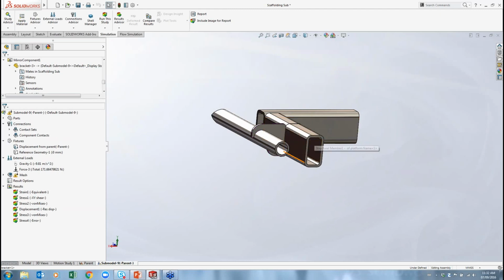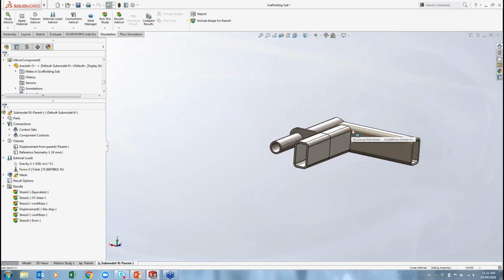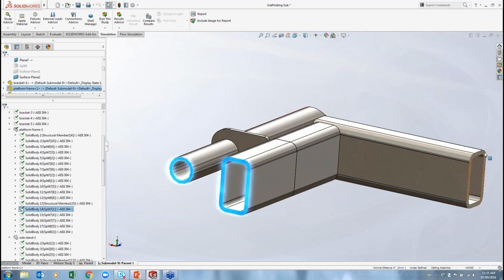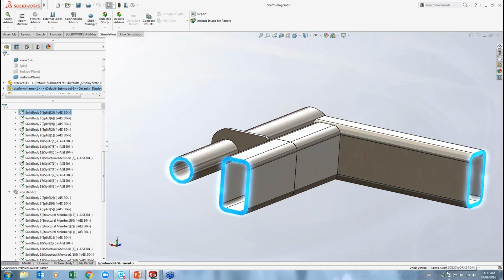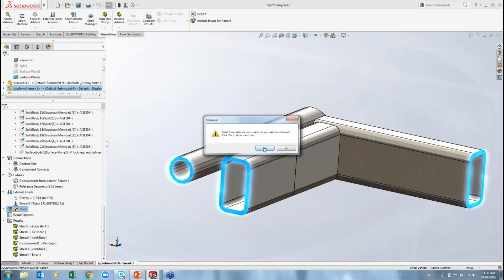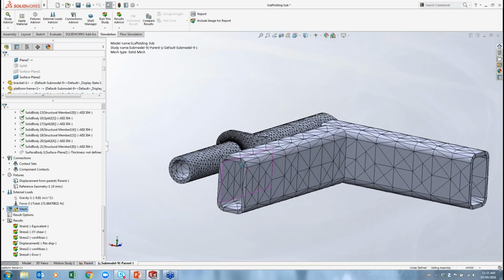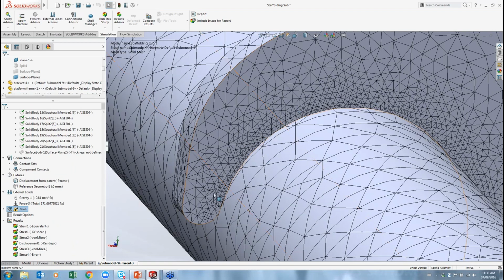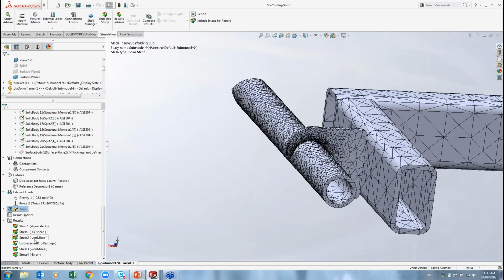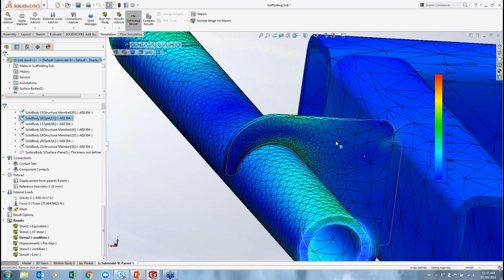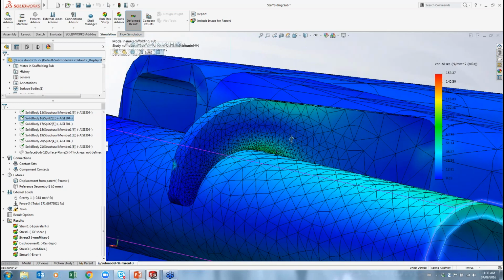Just a few components, but we can see very detailed results on these. Again, the boundary conditions at all the edges here, at all the cut faces, these faces are deforming and behaving like they're connected to the master model. So I can now run through, try a much more detailed mesh on something like this. We can run through and do a mesh like this, very heavy mesh along our contact zones. We see how deep those stresses go.